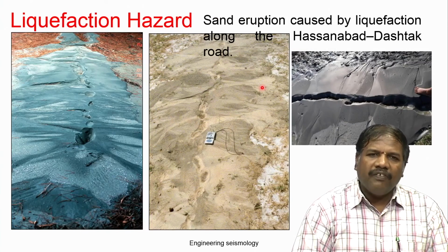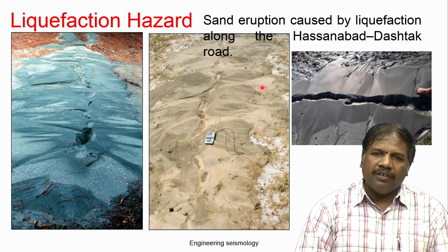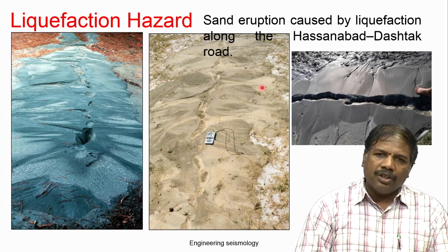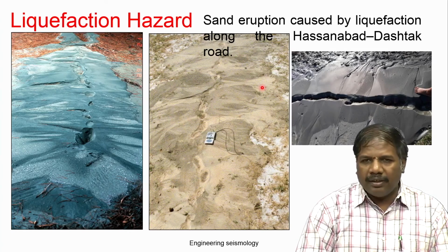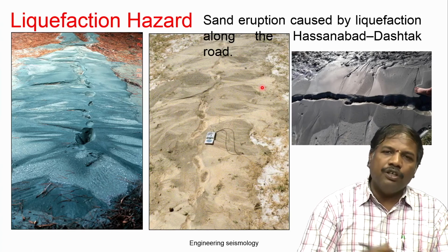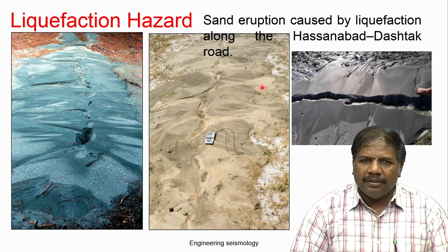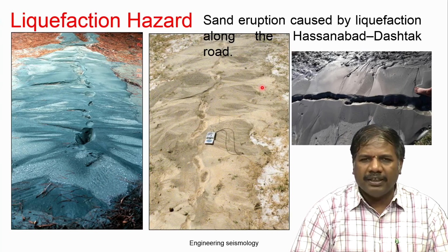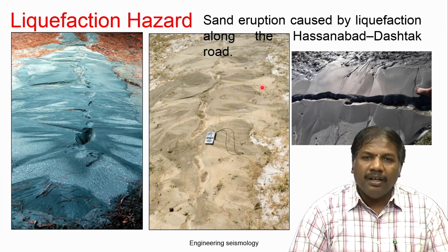Generally, liquefaction basically occurs in cohesionless soil. As I have told you, when the earthquake comes, the cohesionless soils have a free tendency to move. When it is saturated, the effective stress reduces to 0. Okay, during the vibration, that causes instability and an ejection of that material out. So, this is actually a surface feature of liquefaction.